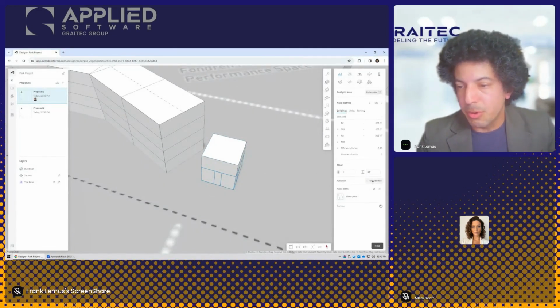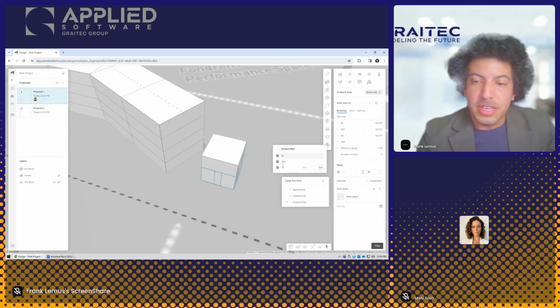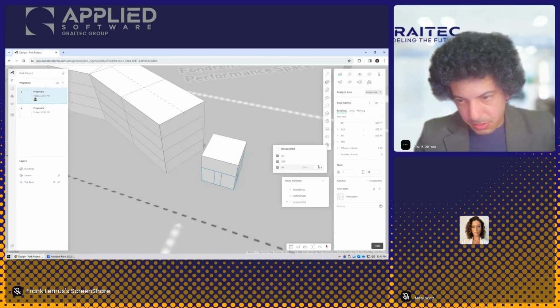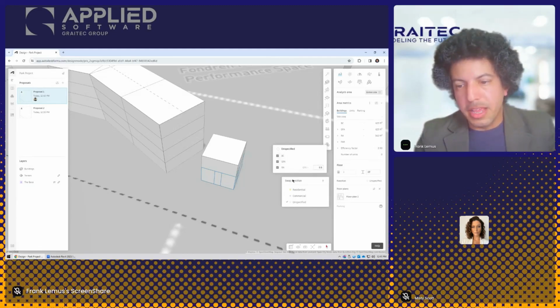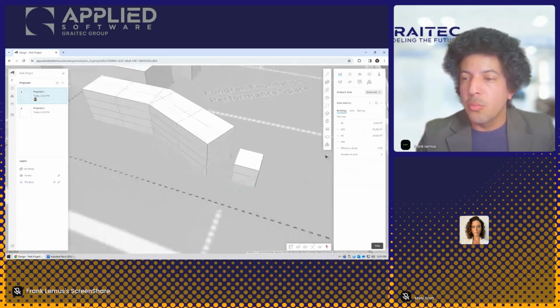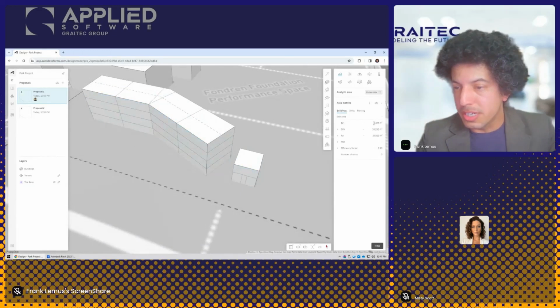I have the function parameter here. It says unspecified, and look at what this all means. Unspecified, if I look at this, tells me, look, as an unspecified element, I will be able to register it under the BC, GFA, I think that means gross floor area, and then RA. And it'll give me the multiplier. The check marks here mean that unspecified will be seen when you look at the analytical data here. So you can see BC is included in that value.